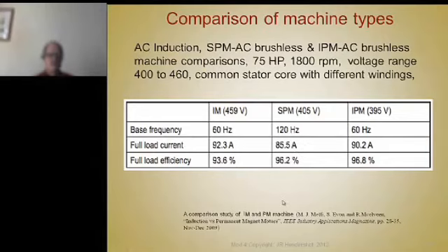The one thing they should have put on here, maybe, I'm pretty sure this was a copper rotor. They should somehow relate and weight the cost of the copper rotor versus the cost of the surface PM motor versus the IPM, because usually the IPM motor is going to use less mass of magnets than the surface magnet, because it gets a torque component from the saliency between the permanent magnets, which we'll look at later.